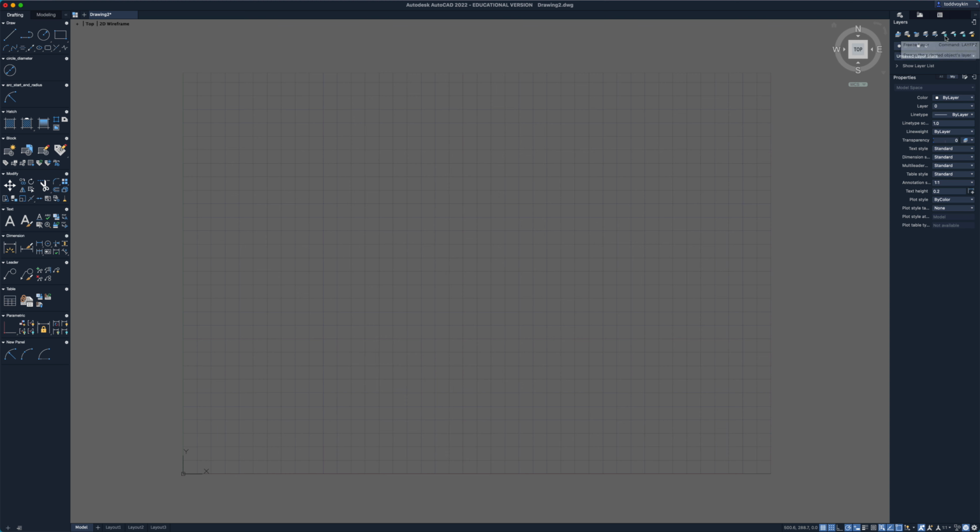So this one right here, which says freeze a layer. Sometimes you'll be going to draw and it just won't allow you to select that layer, and that's because you've frozen it, which means you can't use it anymore. And beside that one is turning the layer off, which means you can't see it, or turning it on, which means you can see it. And beside this one, you've locked the layer so you can't do anything to it.